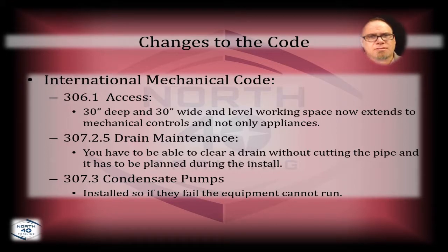Okay, that T being there, because it's part of the actual drain, does not count as part of the planned maintenance procedure, and so you may still be required to put a 3/4 inch flush out in there so that you can get in there and actually clean that drain. Now, it's a small thing. It doesn't add a lot of expense to the job, but it's one more thing. So it's something there for you to think about.